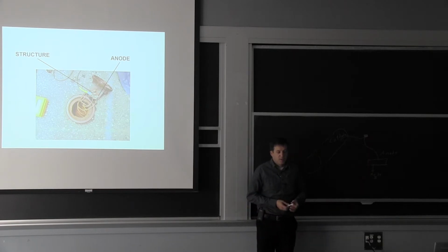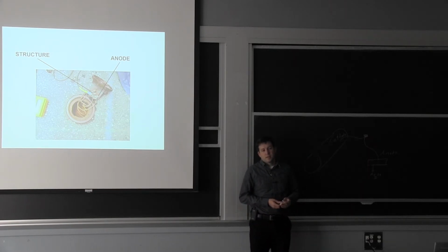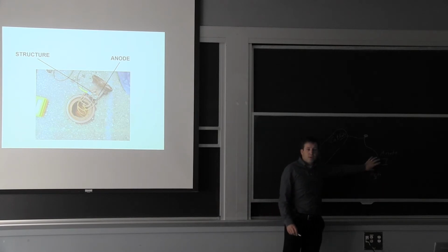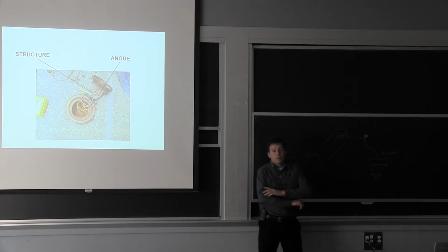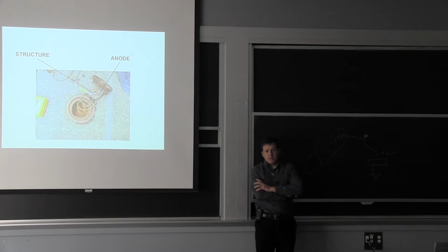It's used for most pipelines, oil and gas pipelines. And again, you can go back and make sure nothing is going on with your sacrificial portion by testing. The issue with those, of course, years and years down the road, is whether the rectifier is being checked. Because if you run out of power on your rectifier, then all of a sudden you're going back to regular corrosion.